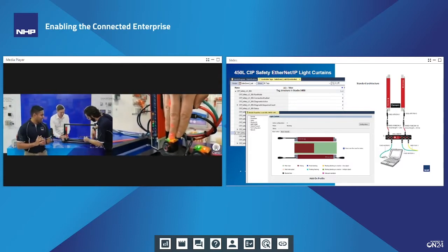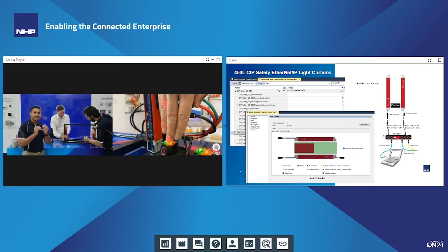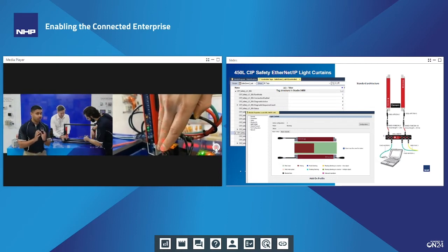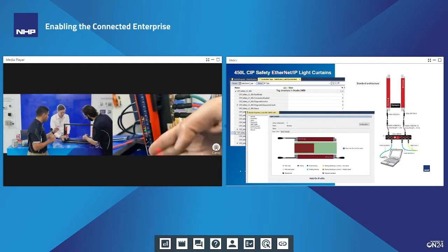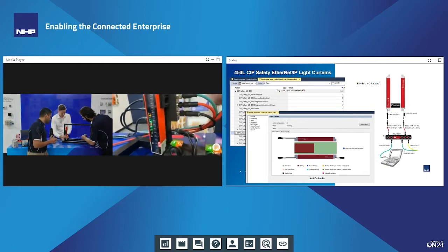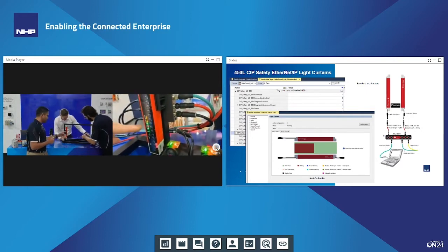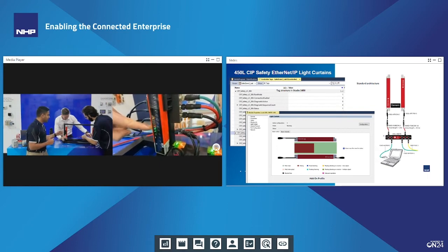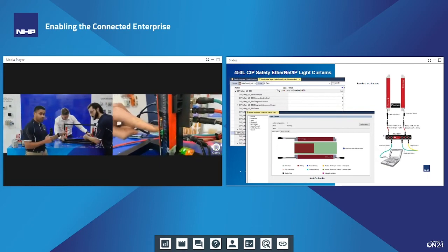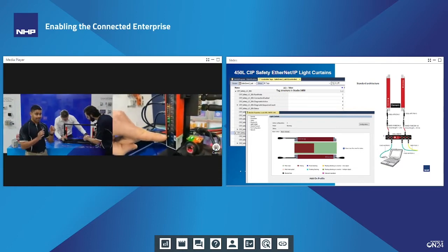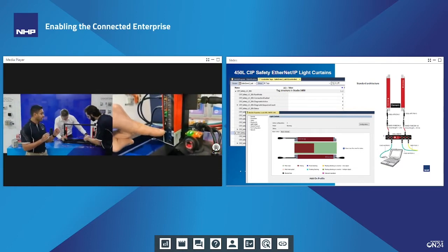What you would notice is the beam intensities of these change, which means the radius of these beams change. Ideally, I want to make note of a couple of things before we go. Jack, could you please show them the less than or greater than signs on the light curtain? That'd be these green ones over here. Correct. I want you to place your focus on those. Now they're off because we're misaligned. I also want you to place your focus on the triangle with the star there. What we're trying to achieve is to have the beam with the highest intensity come between the triangle and flash on the star.